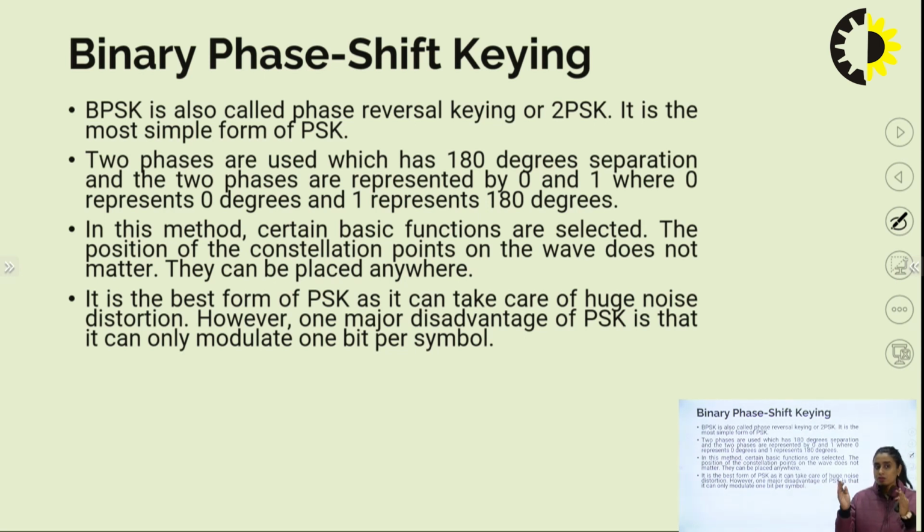Although the phase variations are reducing at higher levels, this increases the receiver complexity, which is required to differentiate the di-bits or tri-bits, and there could be a possibility of error because of noise introduced. When noise is introduced and there is a little phase variation, because of the already existing lower phase variation, the noise can cause the di-bit or the tri-bit to be read as wrong bits, right?